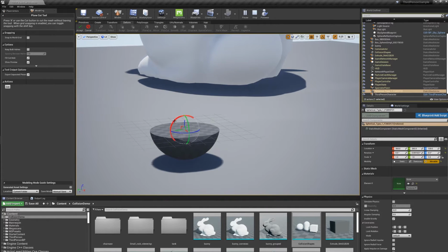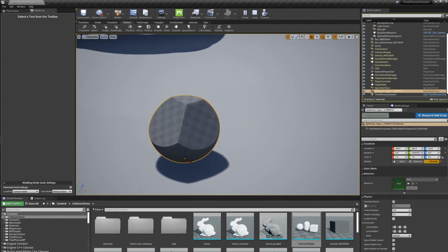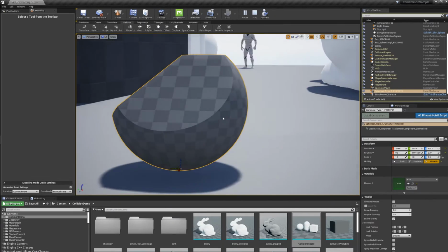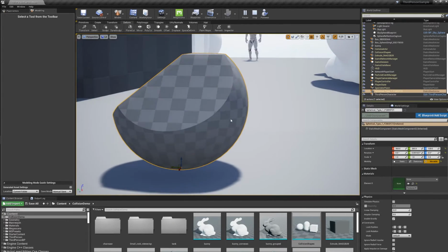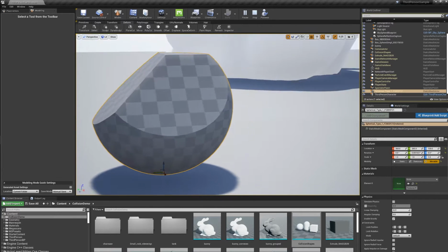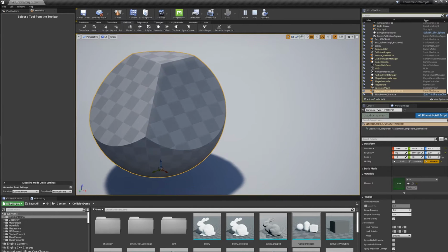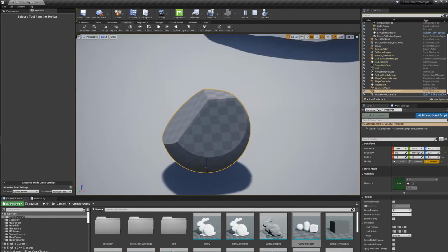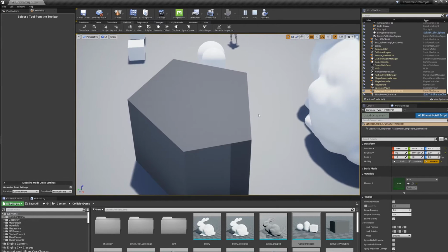So I'm just going to do a few of them here so that I can more thoroughly explain. So you see we've got now these big planar pieces, and I'm cutting away parts of the sphere. And actually, if you think about the sphere as mesh, each of the triangles was basically a little plane cut off of the infinite space is how you should think of it. So I just made the sphere out of a bunch of plane cuts, and now I'm adding more planes. And this is actually how the collision system internally represents convexes, as a set of planes. So only certain shapes can be made this way, right? In particular, I can never cut this sphere with a plane so that it makes an indentation, like that I did on this shape up here.